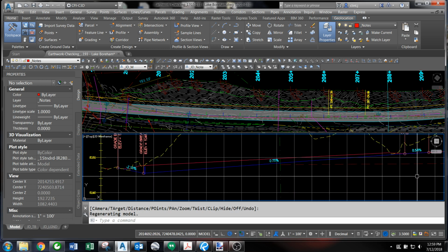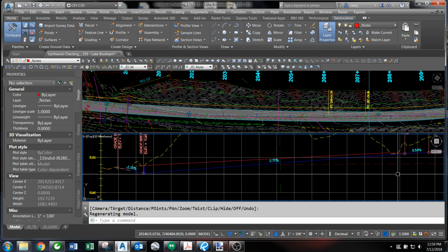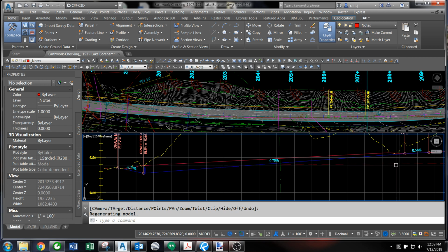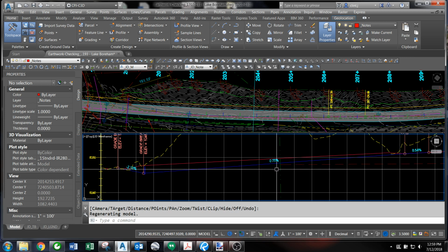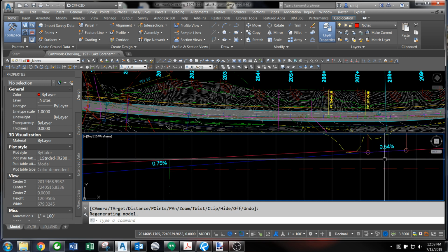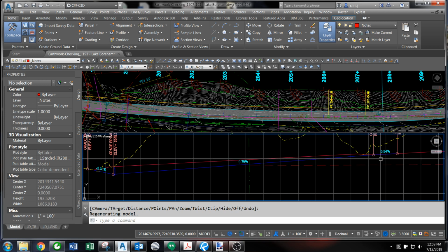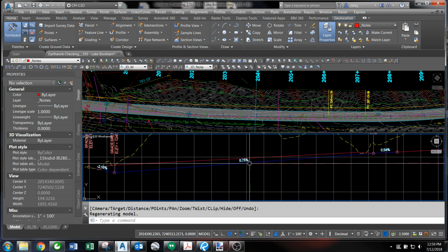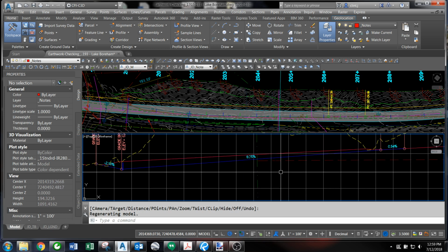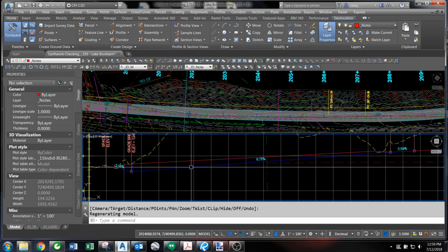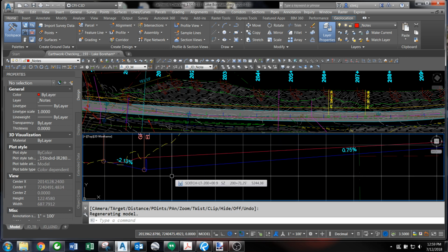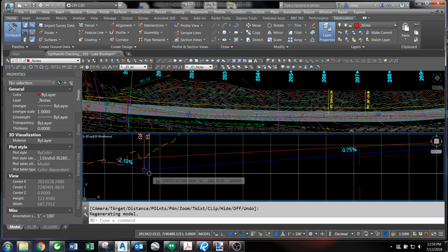We're coming along and just matching ditch lines from upstream, so water should be flowing down. And right at this point, there's almost a spot where you could stick a culvert. But instead, we thought, let's push this down and continue making the water come this way. Granted, these are grades that are low too. They're still 0.5% grades, but they're steeper than what was showing by the typical section if we'd just let it control. We made it so that we could flow this back to this culvert here, and we set the ditch elevation such that the culvert would work.